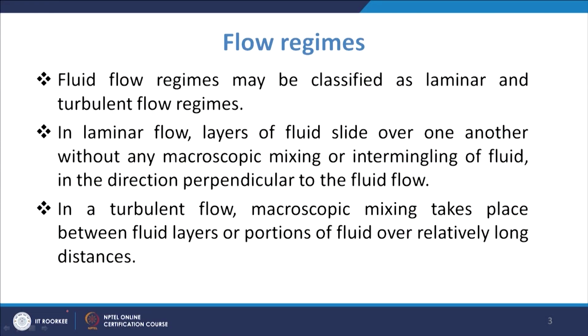As we know, when we talk about the fluid flow, the flow regimes are basically classified as either the laminar or the turbulent flow regime. When we talk about the laminar flow, the layers of fluid will be sliding over one another without any macroscopic mixing or even intermingling of fluid in the direction perpendicular to the fluid flow. So, that is normally the laminar flow.